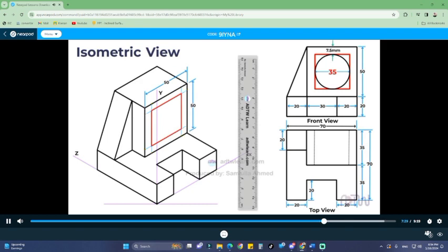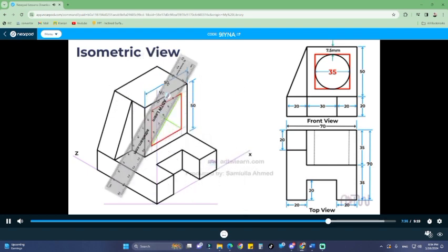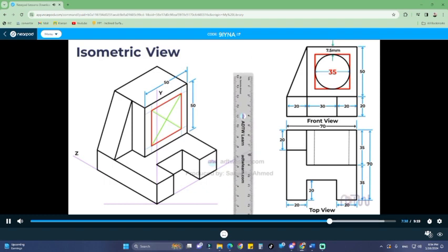Next, draw the diagonals on the square by joining opposite points of the corners. To find the length of the radius needed to draw the circle, we need to divide the side of the square in half. Since the sides of the square are 35 mm, half of that is 17.5 mm. Mark points 17.5 mm away from each corner point of the sides.